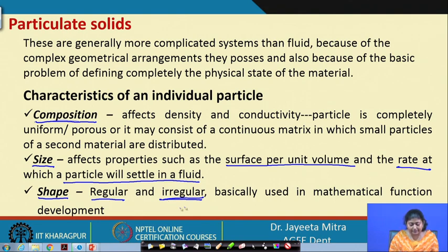We replace the irregular particle and define a certain factor which correlates the irregular with the regular particle, and we take those regular particle sizes into the modeling of the phenomena, because when we want to analyze any particle characteristic or bulk solid flow behavior, we need the regular shaped particle.